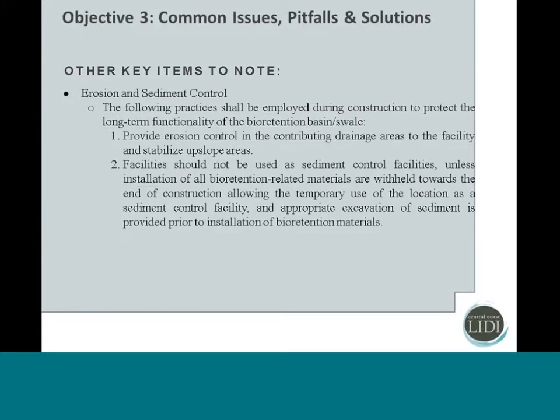So erosion and sediment control, I think every speaker here today has touched on that because it is really important. So, having your proper SWPPP measures and all your temporary BMPs in place during construction to protect these bioretention facilities and not opening them up until the end, until the site is fully stabilized.